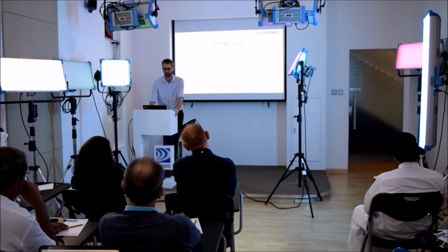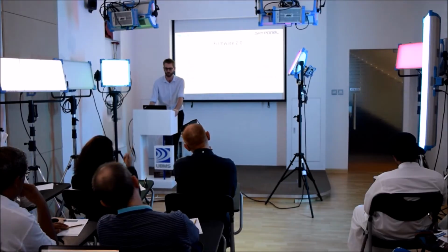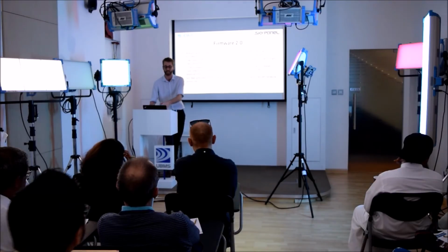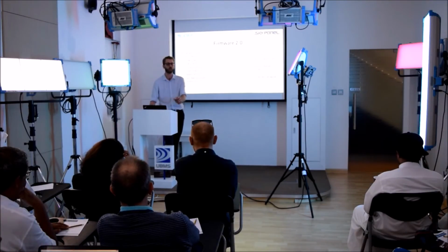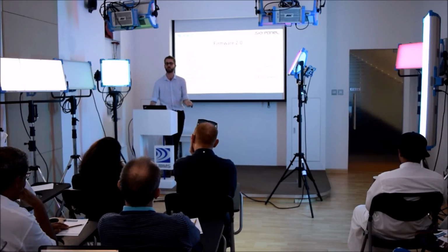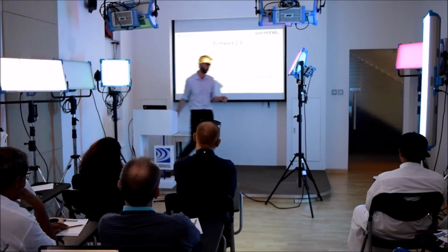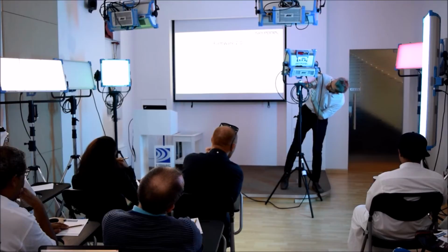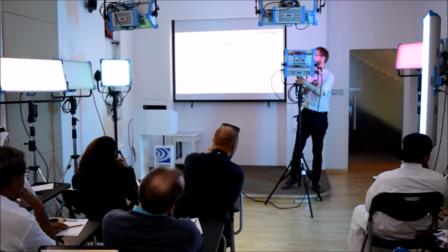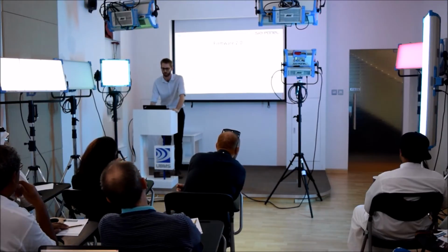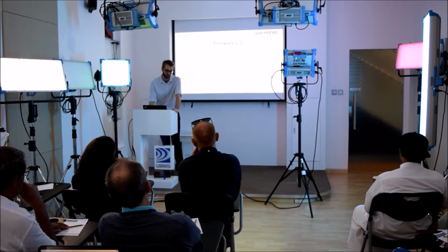And then there's something called ARRI, which provides your normal DMX 512 protocol, and remote device management, but instead of being over a DMX network, it's over a normal Ethernet network protocol. So that's one way that you can use the Ethernet port on the light. It gives you your DMX control but over Ethernet networking protocols. So that's pretty cool.